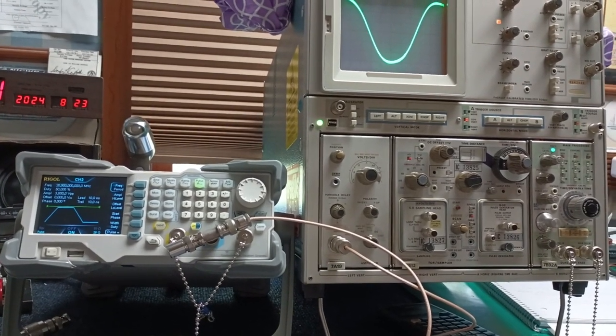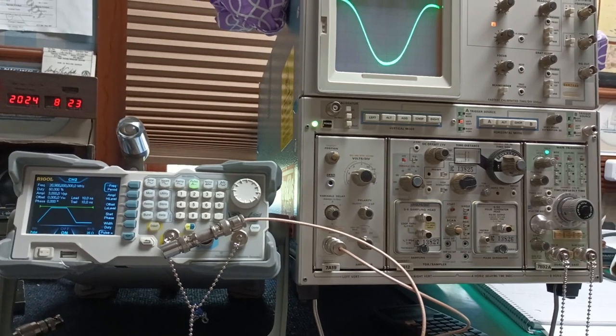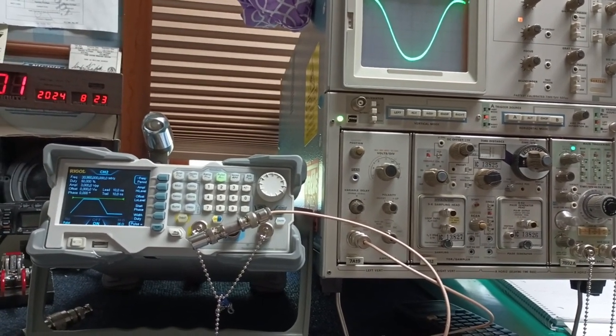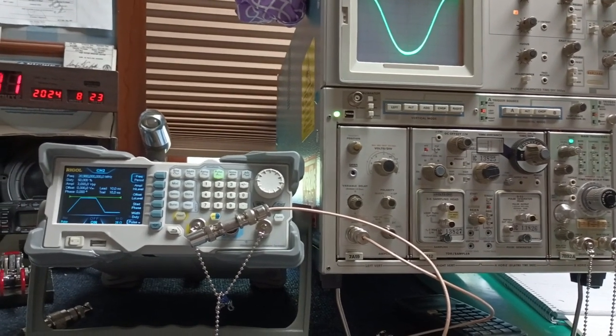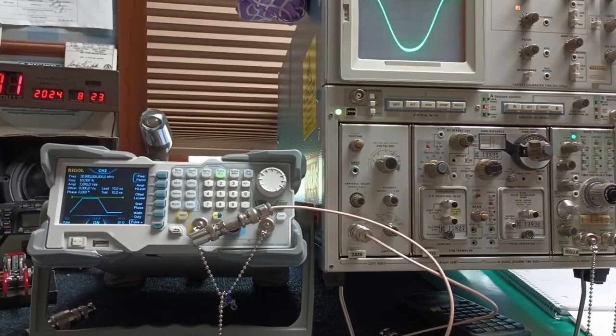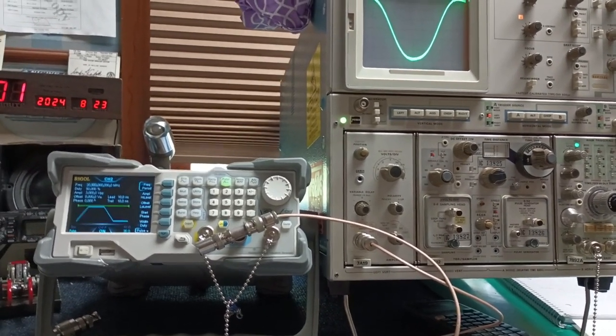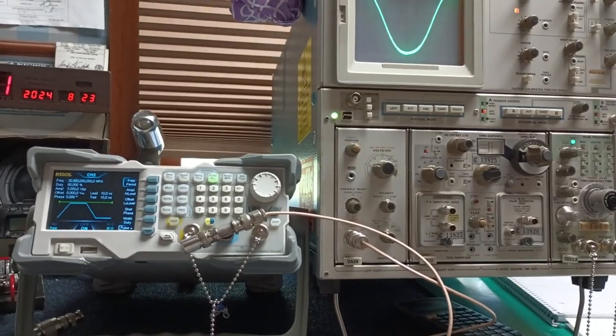I showed you in earlier videos that propagation time out and back on those wires is what the matching really kind of sort of is, in addition to the feed point matching. So there's all kinds of sources that can cause reflected power, but the watt meter cannot distinguish them. And that's why we go to TDR tests.